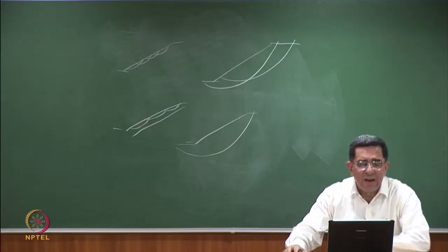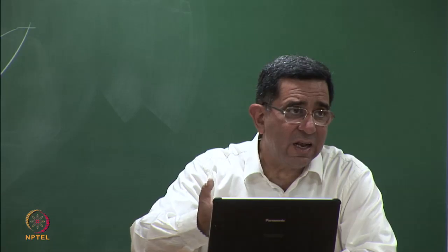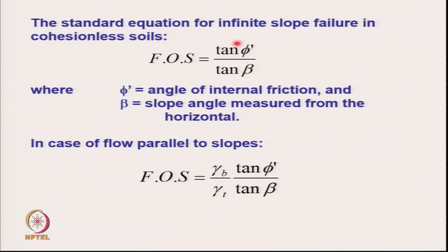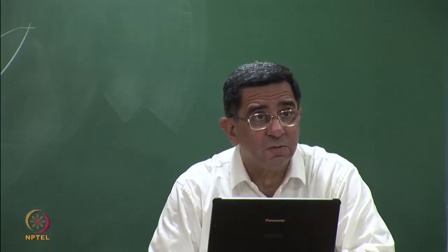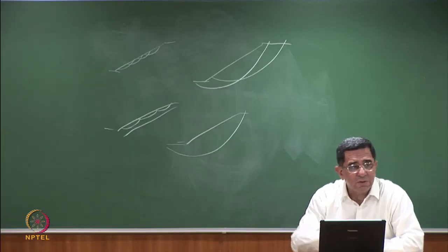So when you have infinite slope analysis, just for simplification of things, in cohesionless soil, because for us ash and tailings are cohesionless, c dash is 0, then a nice equation comes. Factor of safety is equal to tan phi dash by tan beta. Is this equation developed for a circular failure surface or a straight line failure surface? Straight line failure surface parallel to the outer slope. You remember? So is that valid? I am showing you circular, and here I am talking of formula which are.